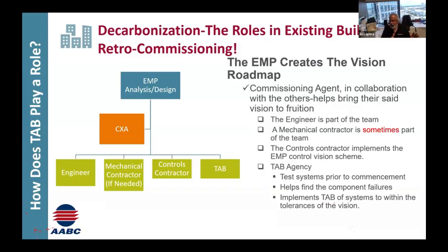This does not meet the design. Have you had any cooling problems that you've yet to tell me about? And are you expecting these air handlers, when we walk away, to be doing 40,000 CFM? The owner, who's also an engineer and the operator of the building, looked at me and goes, why would I want to do that? I go, I don't know, but I don't want you coming back later and going, hey, you're supposed to do 40, they're only doing 28. What's the matter with you? So I'm just telling you, that's why it's very important in the very beginning to do that.